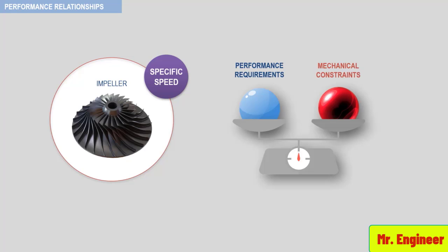Finally, efficiency is presented in this section as a ratio of ideal head to actual head, as depicted on a typical Mollier diagram. In addition, the fan laws are presented showing how increased impeller head can be obtained via speed change in a compressor application.